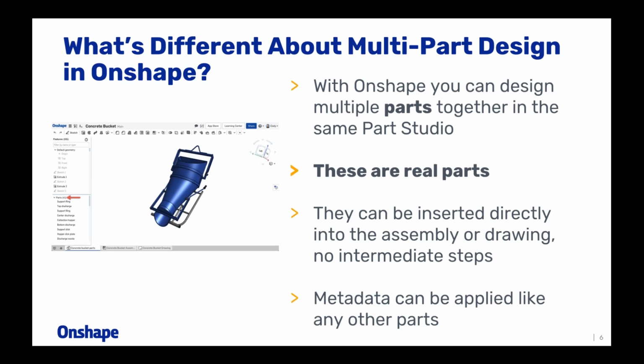And as I mentioned before, there's no difference in terms of metadata or how the model is interacted with, regardless of whether it's modeled in a bottom-up manner in a single tab or a top-down manner in a multi-part part studio. So that's the key thing that I would stress, and it sounds like a simple thing, but it really opens up the workflow for multi-part modeling. If you think about multi-body design, the fact that you had to generate all these files and then insert all these files into the assembly really hampered the update workflow and making design changes.